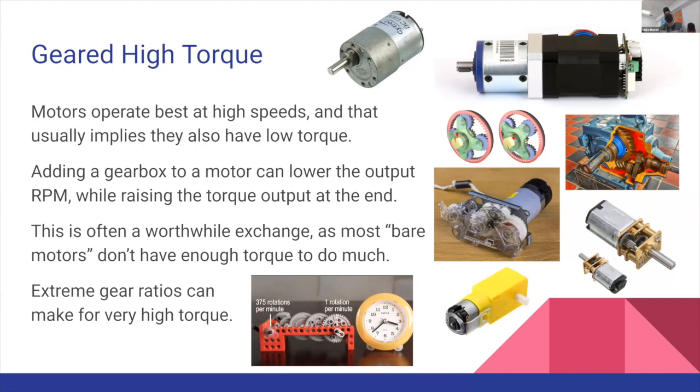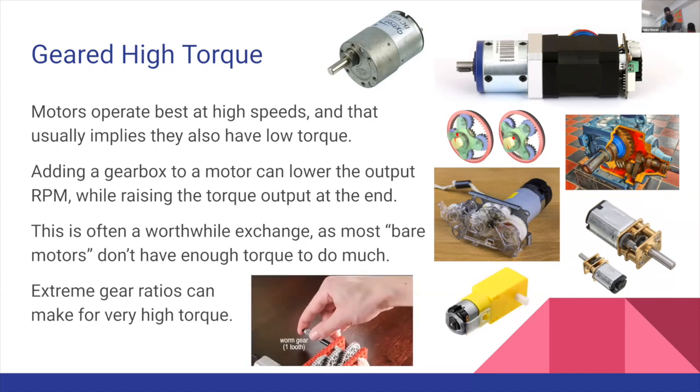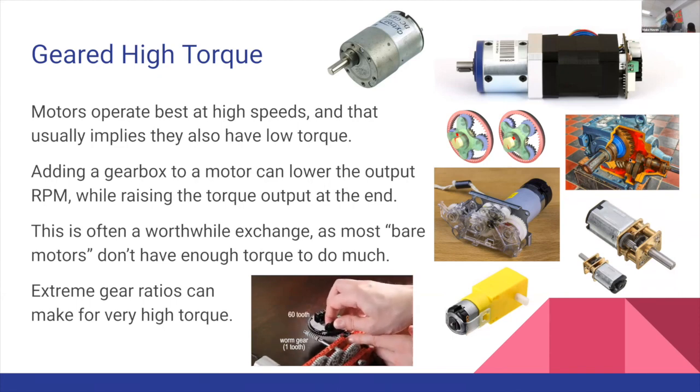Here's a worm gear drive. This is a nice way to not only change your direction 90 degrees, but each one rotation of these advances this big outer gear by just 1 tooth. So the gearing is really aggressive on those. These are often used on something like the Bridgeport.